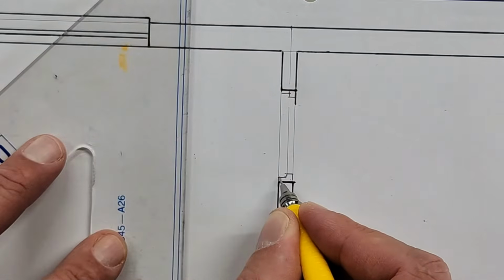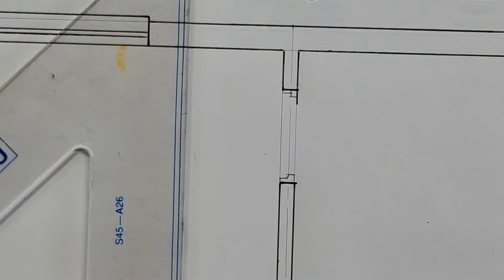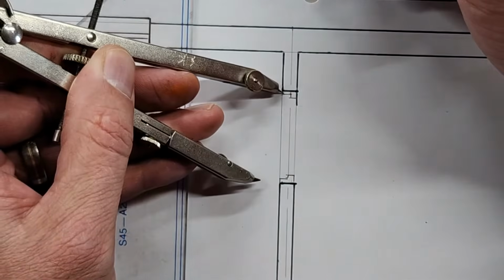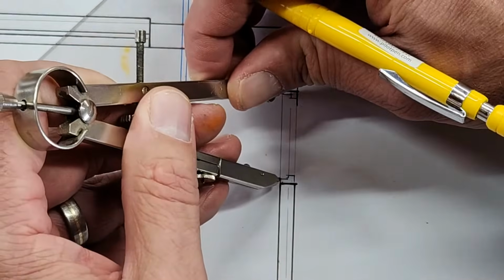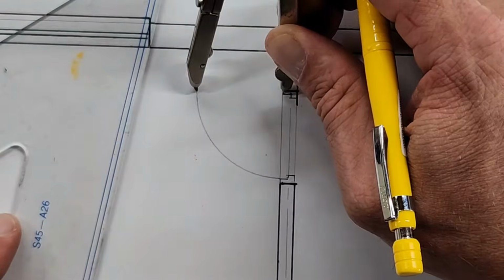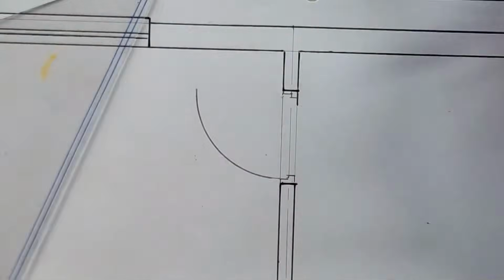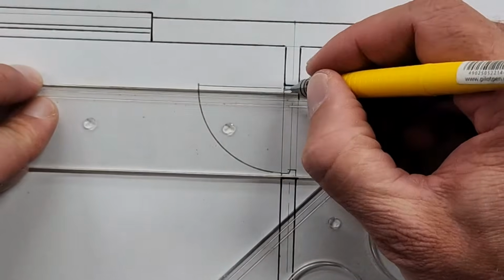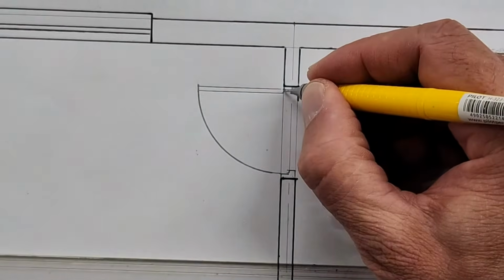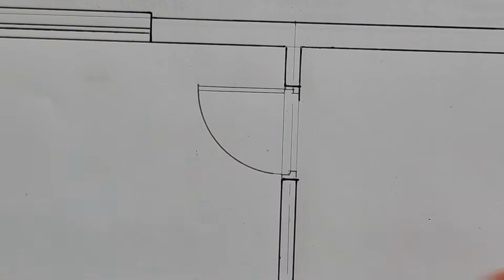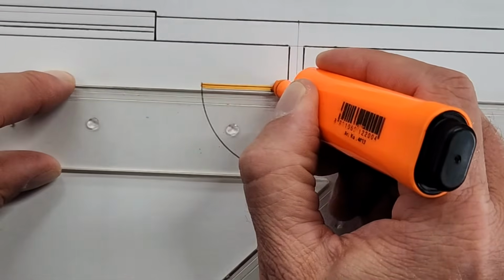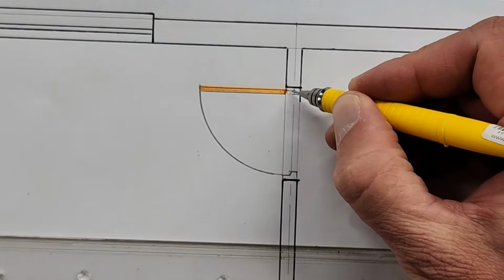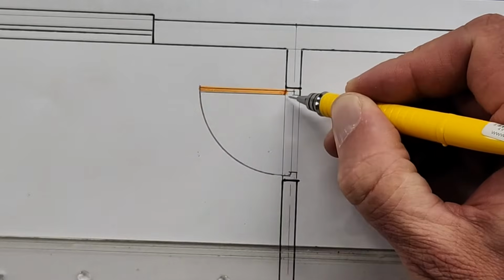Okay, so I think you can see the door frame there, and then the swing of that door, the hinge is on that outside corner. So look at where that compass goes, right there, and there, and it swings in line with that line. Okay, and now from this point we're going to have that's the actual door we're drawing in here. That's also closed. So that door, if it's in the open position, just for your understanding, there it is, in the open position. If that would swing closed, the back of that door will fit into this recess here.